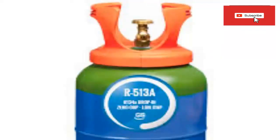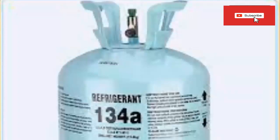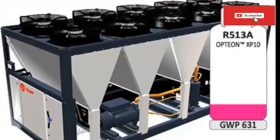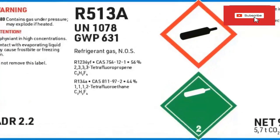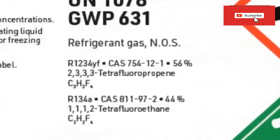Let's start by saying that R513a has been developed to replace R134a refrigerant gas in new and old low and medium temperature refrigeration equipment, as well as high temperature applications, such as chiller-type water chillers. R513a is generated by mixing R134a refrigerant plus R1234yf gas.